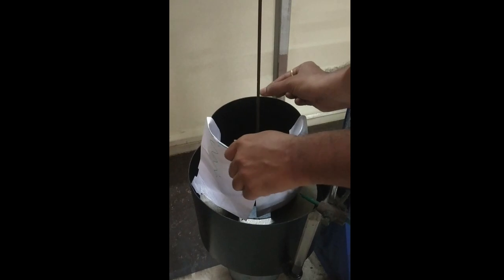Now what exactly is torsional vibration? It is the vibration in which each and every particle of the body moves approximately in a circle about the axis of the shaft. As far as the procedure is concerned, we are just providing this system torsional vibration, and we are going to record the number of oscillations upon time. That gives us the experimental natural frequency.